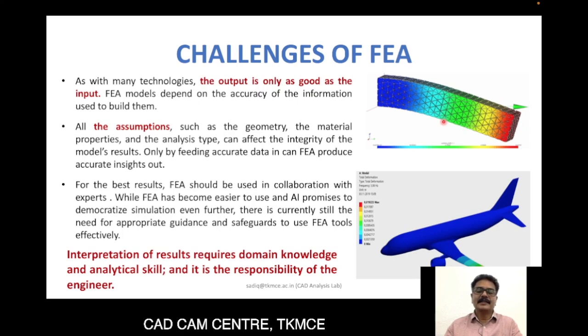As I said, in the case of the design of a bench, if the deflection that you get is say 5 millimeter over here, whether it is acceptable or not is your decision. When I design a chair, obviously when we sit on a chair there can be deflection, say even 5 centimeter deflection can be there. For a mild steel tube for the chair, when you analyze it, if there is 5 centimeter deflection, is it fine or not, that is your interpretation.